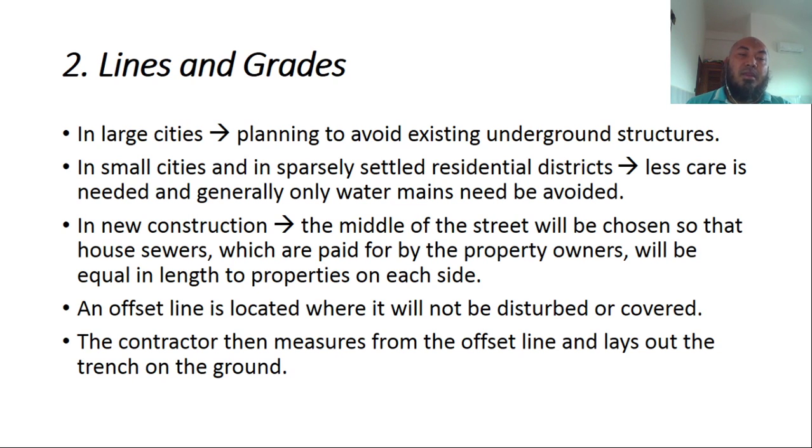This is at the beginning of the job. So the offset, we have the center line. After that, we offset the line, and this offset line should not be obscured. It has to be seen. And then the contractor measures from the offset line and lays out the trench on the ground.